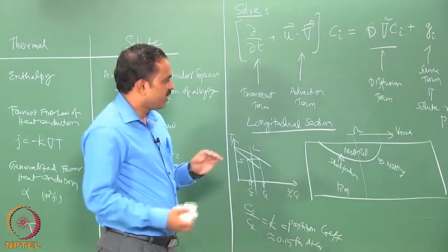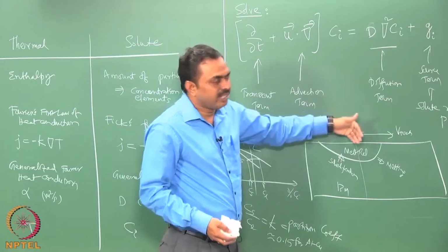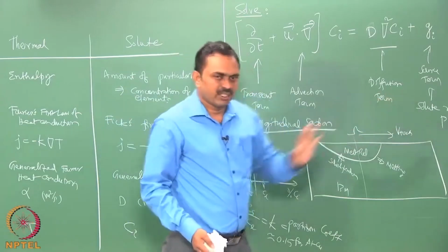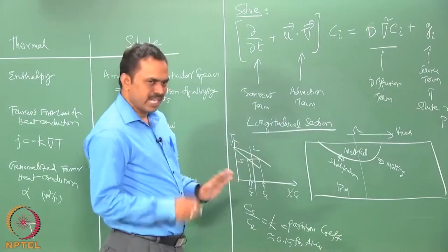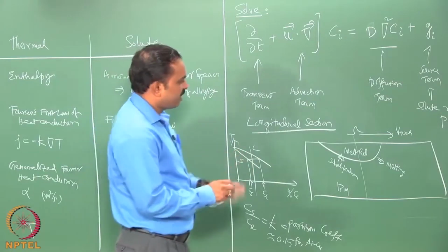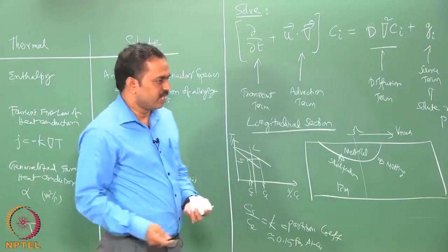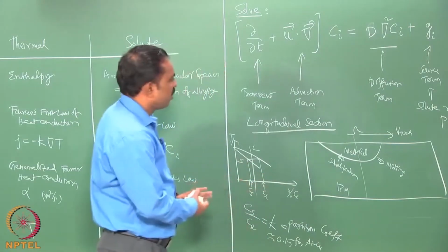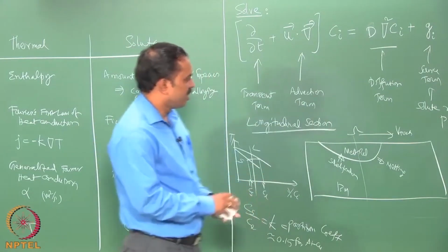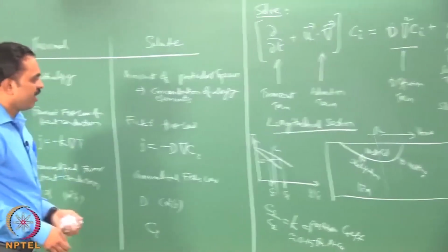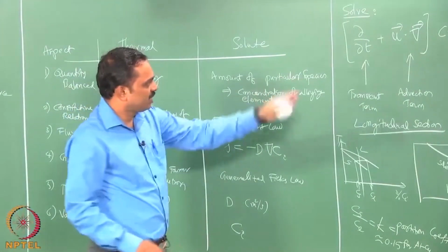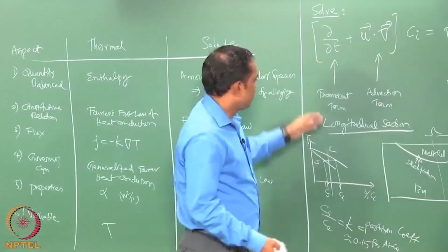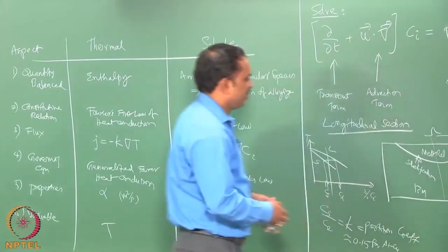So, that at the system scale really not much of flux is getting dumped into the melt pool. In other words, the melt pool as it moves along, the concentration does not change with time, because there are reasons to believe that, and that will be evident after we complete the microscale model of this particular solute transfer. So, at this moment we can say that if at all you want, you could actually take the special term to be the solute rejection due to partitioning, and otherwise you can just ignore that term and pretend that the governing equation is having only the 3 terms, namely transient, advection and diffusion term.